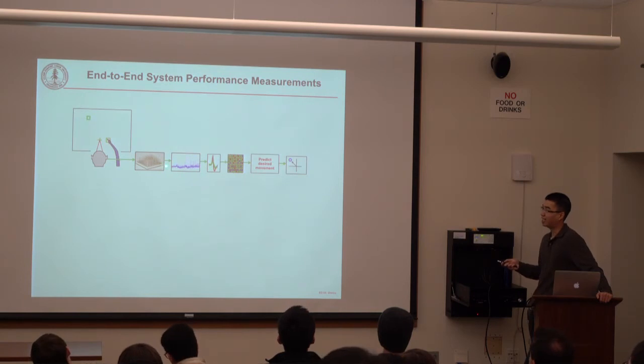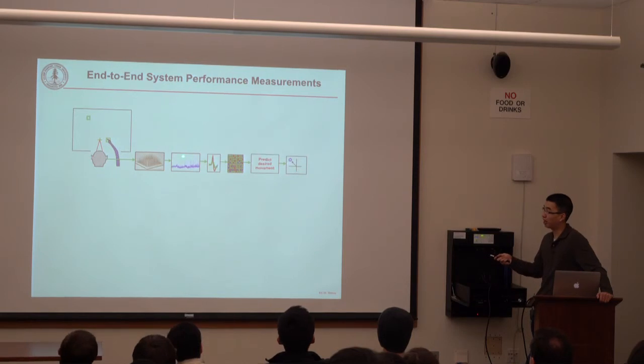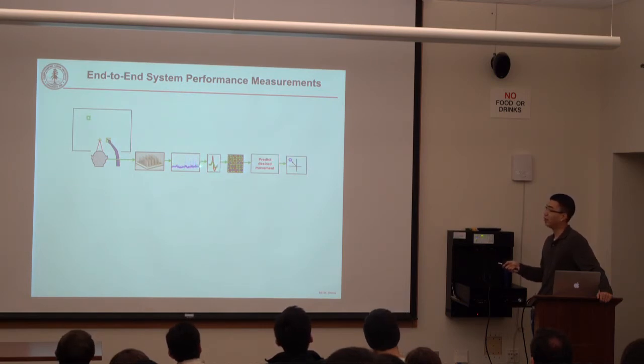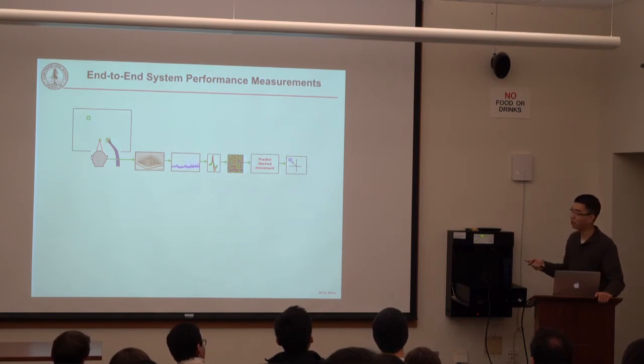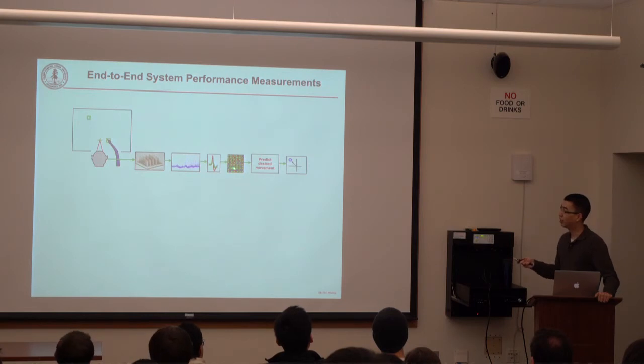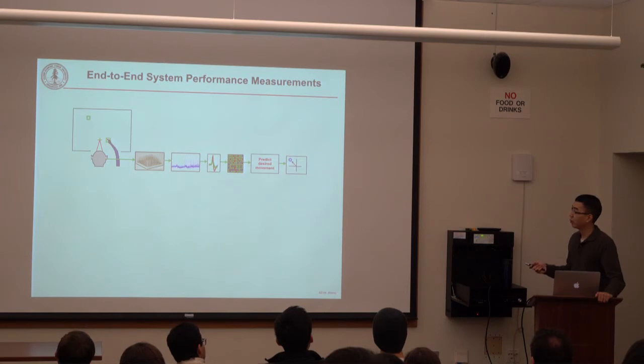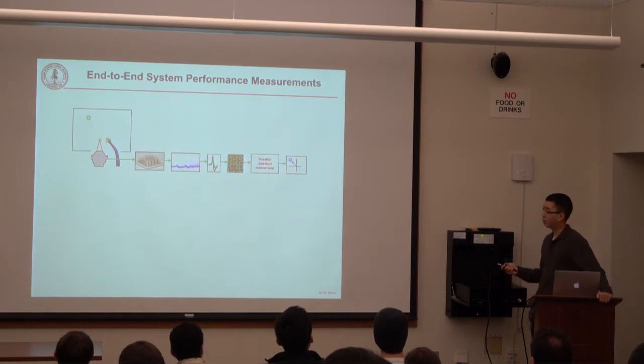From this, we high-pass filter the signal to remove the slow, low-frequency potential, so we can draw a threshold to reliably detect the spikes. That threshold will give us multiple spikes on each electrode, and from there on out, we'll spike sort these different spikes. Then we're going to build the tuning curves, the heat maps that I just showed you. That's basically a tuning curve. We'll build a tuning curve for each of these neurons, and then across all the neurons that we have, we're going to be able to measure their firing rates.